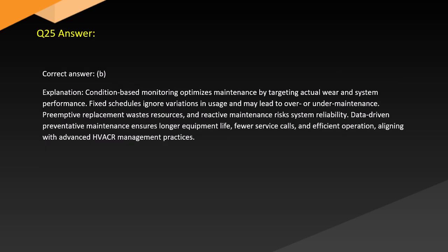Answer. Correct answer: B. Explanation. Condition-based monitoring optimizes maintenance by targeting actual wear and system performance. Fixed schedules ignore variations in usage and may lead to over or under maintenance. Preemptive replacement wastes resources and reactive maintenance risks system reliability. Data-driven preventative maintenance ensures longer equipment life, fewer service calls, and efficient operation, aligning with HVACR management practices.